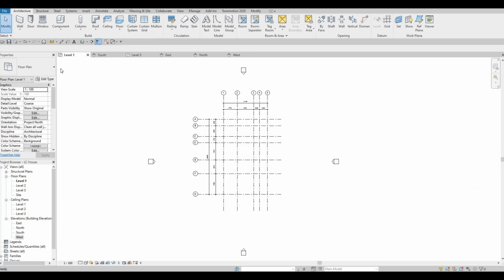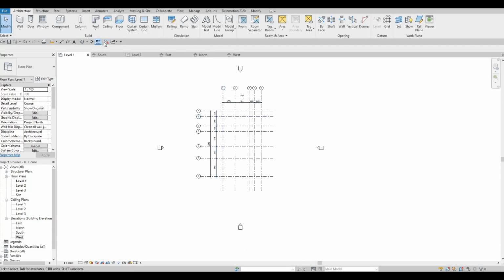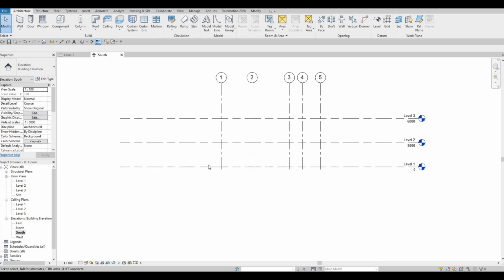Let's go back to level 1. And then here you can select close inactive views. So basically only level 1 will stay because all of this will be closed. All of those are not being used anyway, and sometimes it's just dragging some space along. So might as well clean up when you're doing this. So select that, and then everything will close. Click on save again.